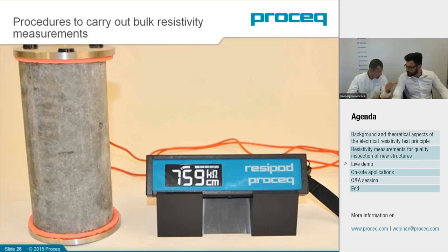Next, I'm sorry, since we're just in the practical part and there is somebody asking for the option that we provide for foam tips instead of the metal ones that we have. Normally, we recommend using the standard ones, which probably provide a quicker and more stable reading. They can even scratch the surface some. The foam tips are to be used whenever you are on a very insulating material, where not enough current is driven, then okay, go with the foam tips. But as a rule of thumb, stick to the basic. Yeah, that's a good starting point. Fantastic. You just got to make sure that there's enough water in the pores of these probes.